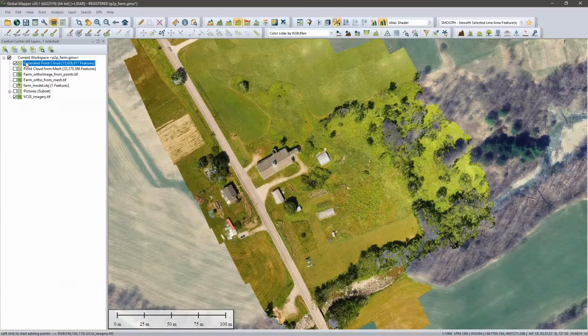And I think Anthony did a pretty good job of simplifying what's going on under the hood here. I don't know if I'll go into too much detail, but essentially the algorithm is doing triangulation of those camera positions using that principal point and figuring out, in three-dimensional space, where the camera was, and it knows what direction it's looking, and it can do some basic image matching to figure out features that are the same in multiple images, and then it's going to triangulate those locations. And so that's what we get from that direct triangulation, and then densification, adding in all the extra pixels that it couldn't quite match exactly as features.